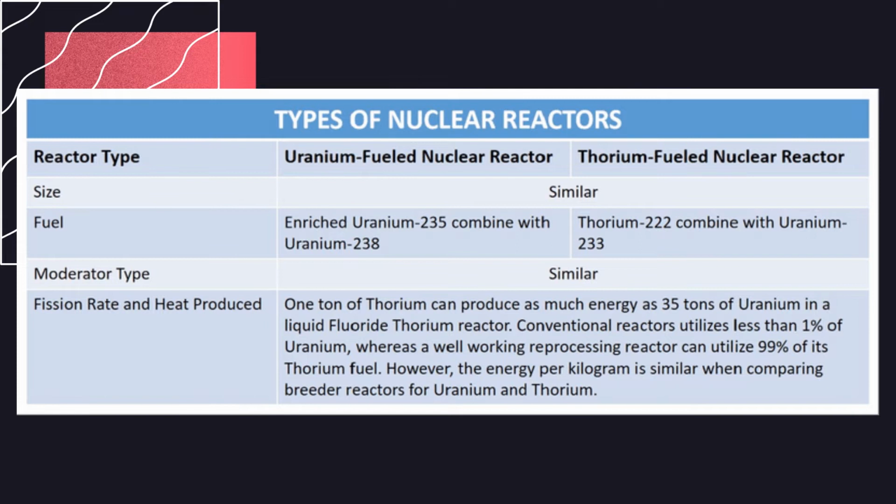First and foremost, about the size of the reactors between uranium and thorium, what will be the difference? It is basically shifting the fuel element from enriched uranium to thorium combined with uranium fuel from plant to plant. This means replacing the fuel element will not enlarge the size of the nuclear power plant by a factor of 1.5 times, while only making the nuclear reactor section slightly bigger or smaller. The balance of the nuclear island, which usually occupies most of the space, is unaffected.